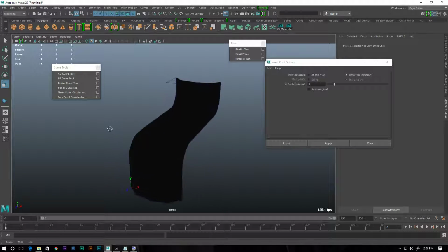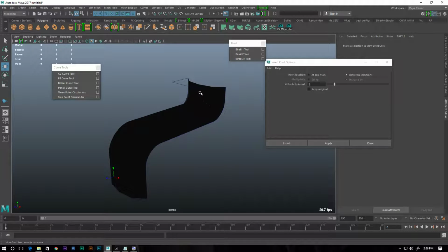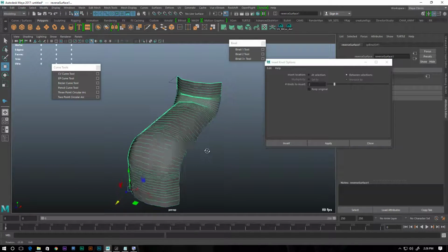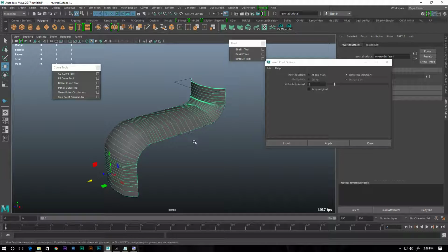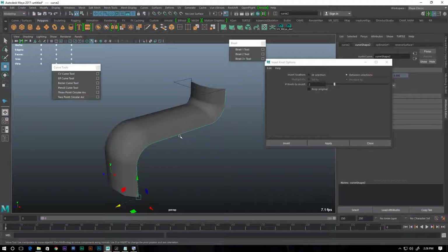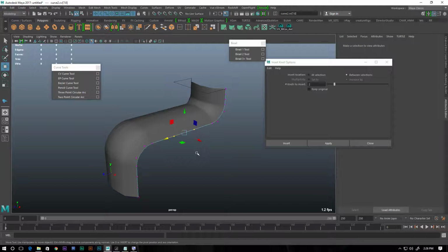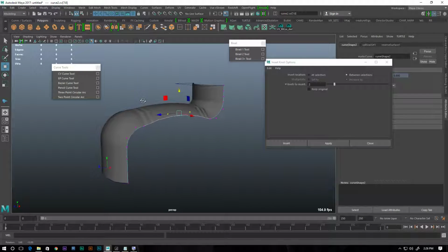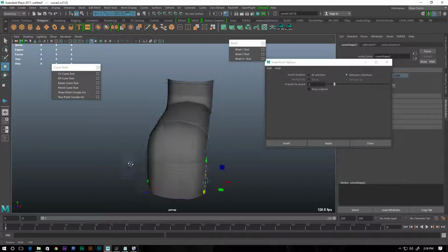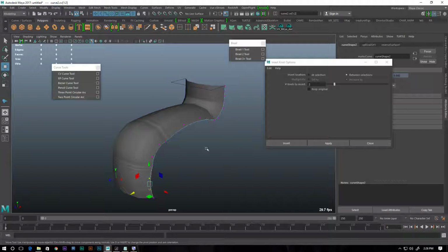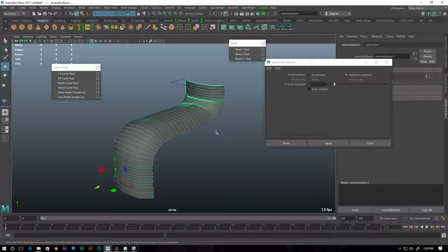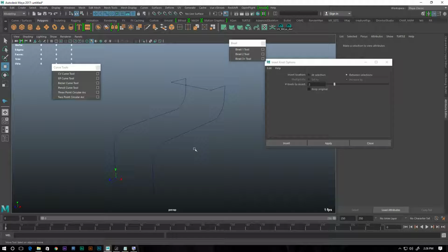And actually we have this thing, and you can say, well, we can achieve this same shape. I'll go to the surfaces, reverse direction. You can say we can achieve those shapes just by extruding a curve along one profile. But if we select this curve and go to the control vertices, you can see that we can make a variation of these shapes along this curve. So we can have 2 different rails and one profile differently extruded along those 2 rails. And this is one of the options.